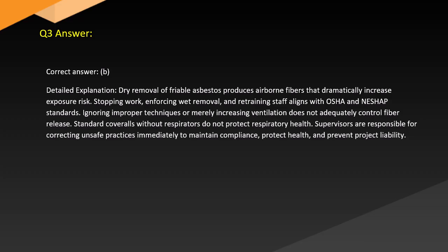Ignoring improper techniques or merely increasing ventilation does not adequately control fiber release. Standard coveralls without respirators do not protect respiratory health. Supervisors are responsible for correcting unsafe practices immediately to maintain compliance, protect health, and prevent project liability.